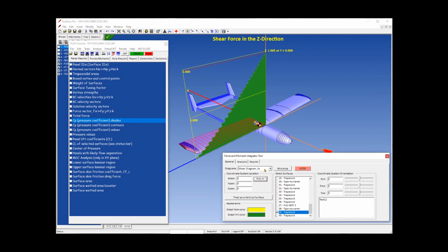Recall that this is a radio-controlled airplane that weighs 2.57 pounds. The model is untrimmed, which is why this force is so much larger than it should be for 1G flight. This highlights that in order to use the tool correctly, you must first trim the aircraft at condition.